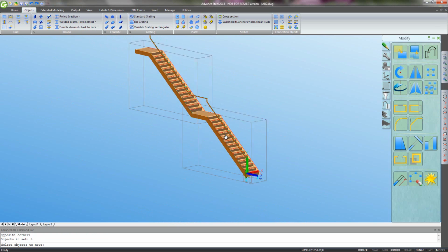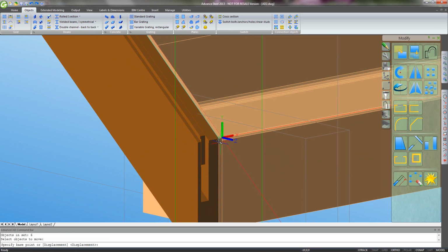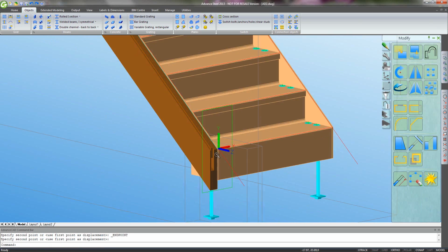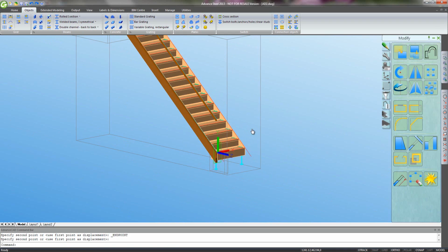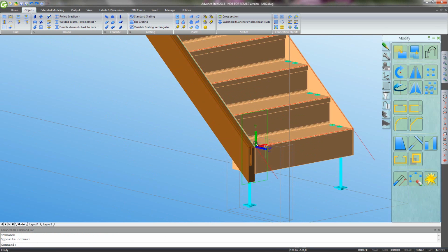Now actually these top beams need to be moved across a little bit because the plane the glass goes in is a little offset between the two beams, so just move them the appropriate amount across, like so. And they're now in the correct position, so the glass is all in one plane. So the next move is to start creating some glass infill panels.